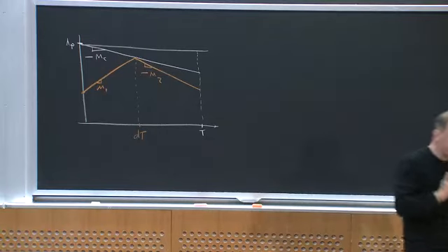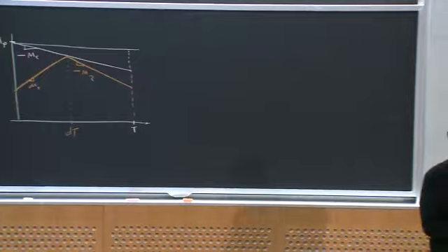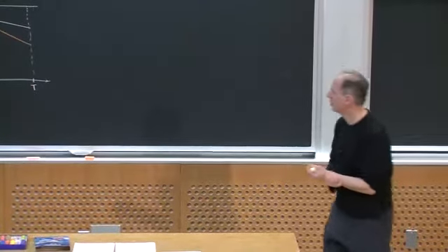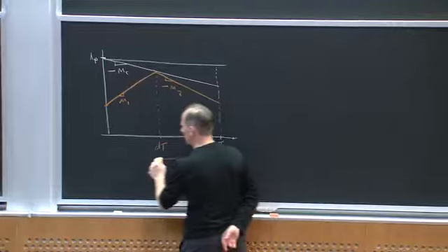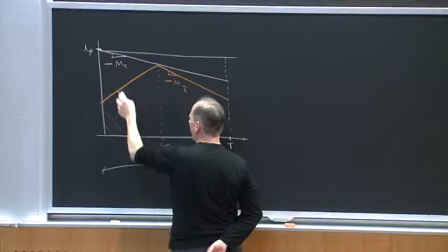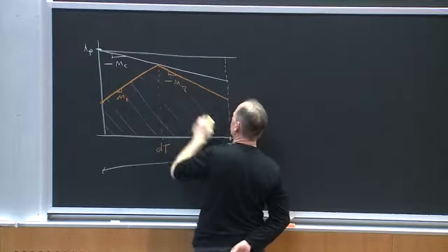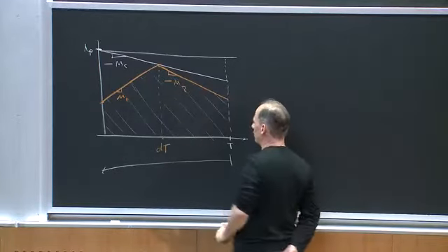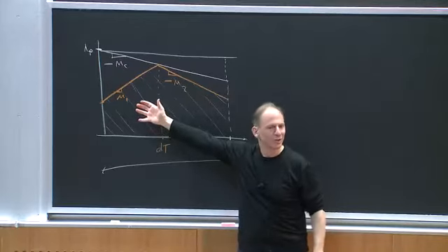And I'm not going to do that by local averaging. What I'm going to do is make a geometric approximation. Right, I'm going to say, okay, let me look over this window and say the average of this waveform, the average of this current, is the local average. Okay?